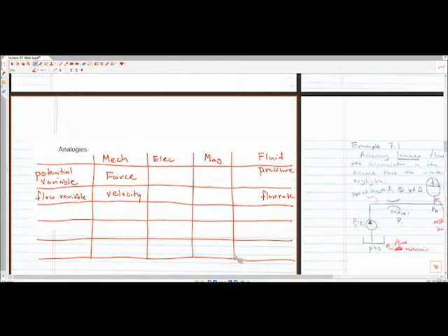And then we have components. So these are variables that we talk about here in terms of something that is a state of the system or something that drives the system. We also have components. So a mechanical system, we often talk about being composed of mass spring dampers. With fluidic systems, we have resistors, we have fluidic capacitors, we have then fluidic inertances. And so we have loss components in a given mechanical system. We have potential energy storage. And we have kinetic energy storage in all these systems.